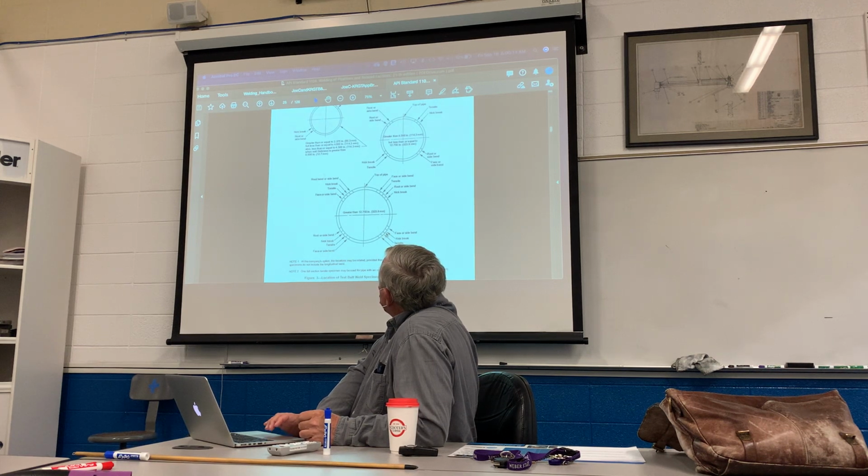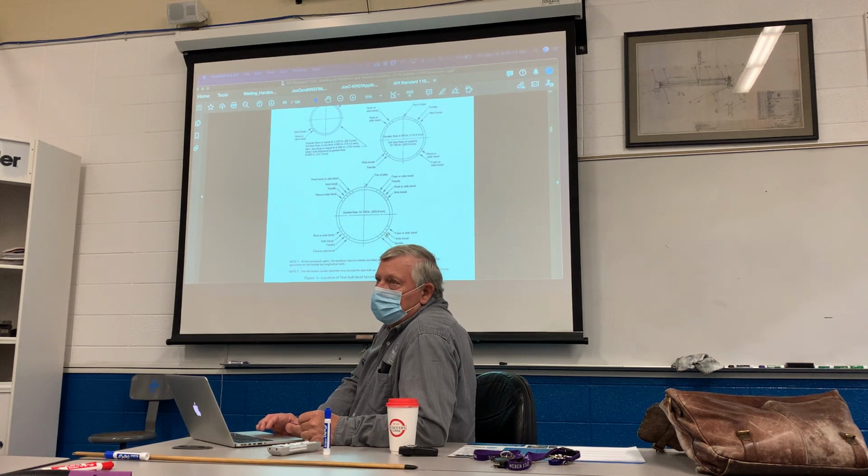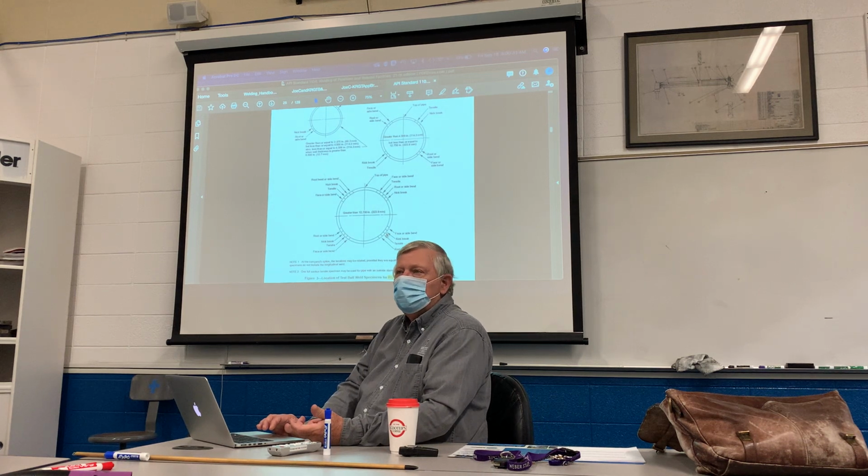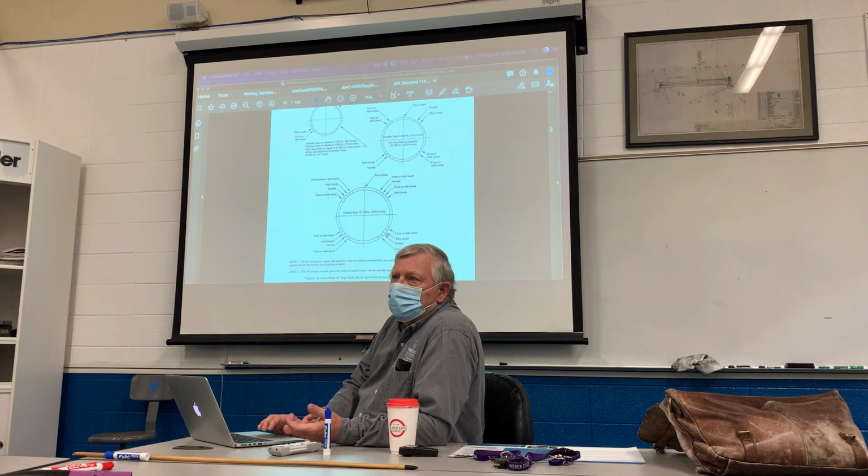All right. And I just got called on this yesterday. I had an urgent phone call when I walked out of the building yesterday from a company that I tested welders for this last summer. And they said, hey, did you guys do nick breaks on their branch tests? Yes, I did. It's not on your procedure. It's not on your WQR. Oh, really? I'll have to take a look and see.